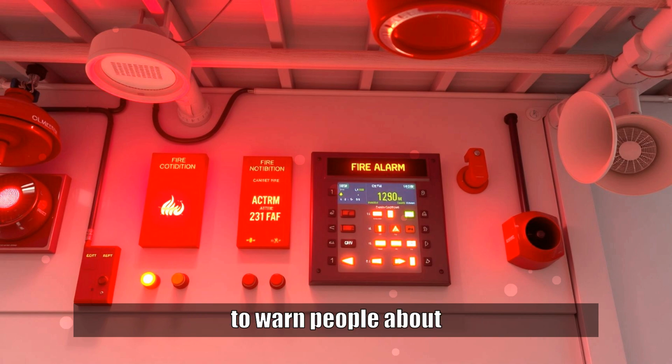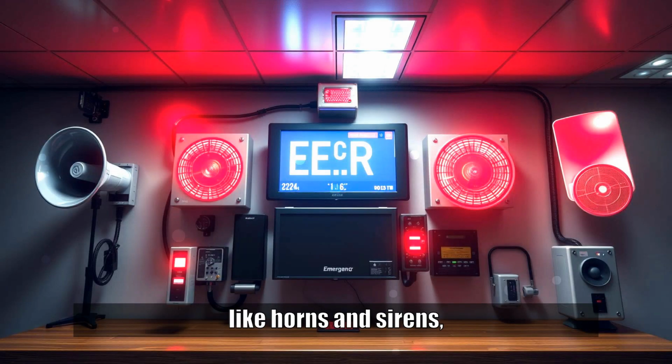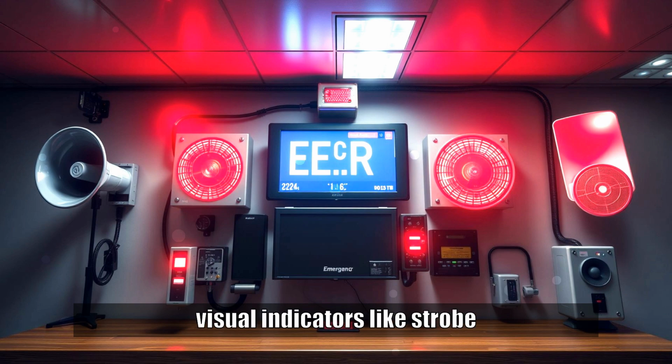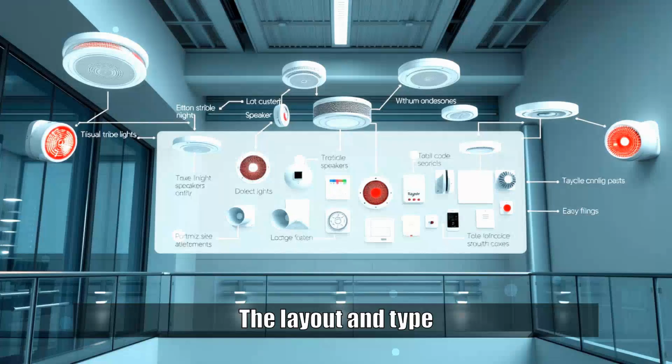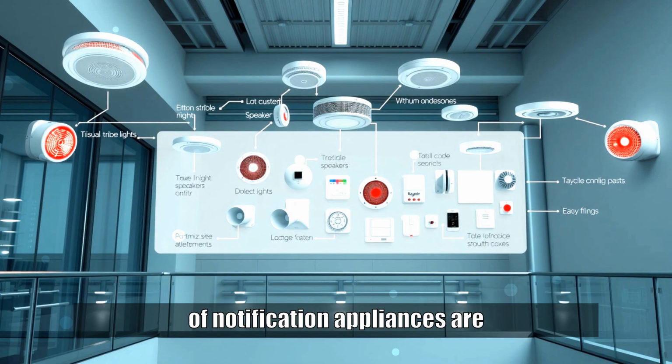system's output devices used to warn people about the emergency. These include audible alarms like horns and sirens, visual indicators like strobe lights, and voice evacuation systems that broadcast clear spoken instructions. Some systems use tactile devices like vibrating pads for the hearing impaired. The layout and type of notification appliances are carefully planned to ensure all building occupants are reached promptly, even in noisy environments or areas where hearing is impaired.